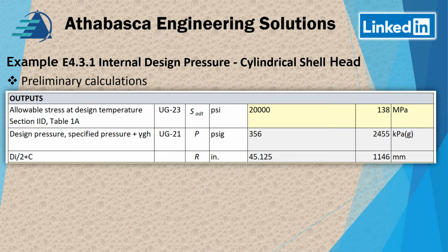grade 70N material. And in this example, we didn't have any head in this tank because perhaps it was a gas, but in another example, you'd have to make that adjustment for the hydraulic head, and you have to go to the very bottom of the vessel and assume the vessel's totally full. This is then sort of the normal case. So in this case, we've adjusted it.